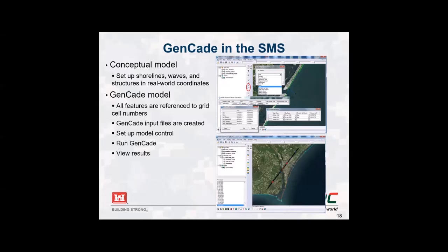Here's just GenCade inside of SMS. So what you do is you set up GenCade. That's the old slide deck. You set up GenCade with an SMS as like a conceptual model. So basically, you draw all the various features with SMS. So you draw the shoreline, you draw the regional contour, you put the location of the groins and the jetties